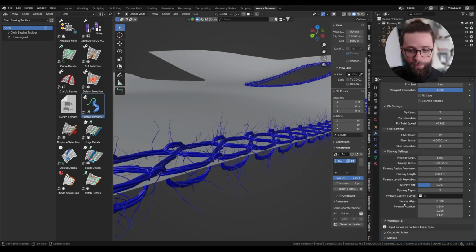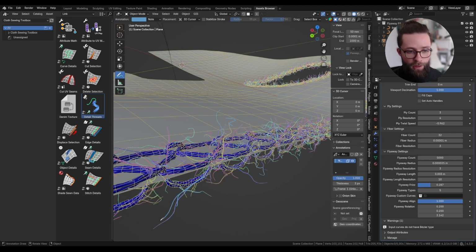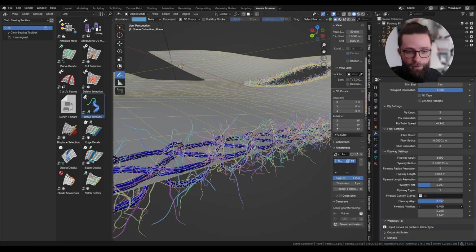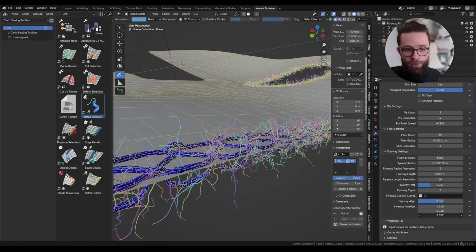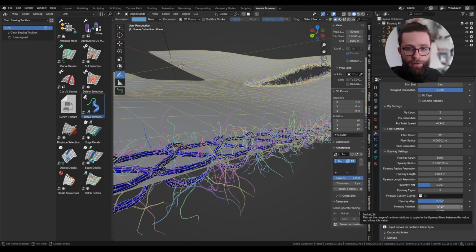The next parameter, Flyaway Align, tries to align the fibers more or less along the generating curve. So when it is set to 1, the fibers are trying to follow the tangent of the curve which is generating them, but when it is set to 0, they might stick out way more outside of the mesh. And the final vector parameter is just some base value for the random rotation, which allows to change the look of everything really easily around the 3 axes of each individual fiber.